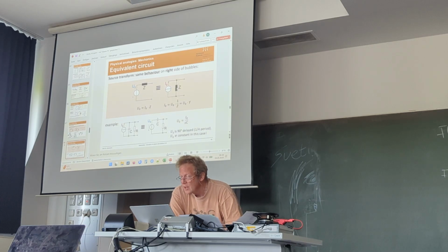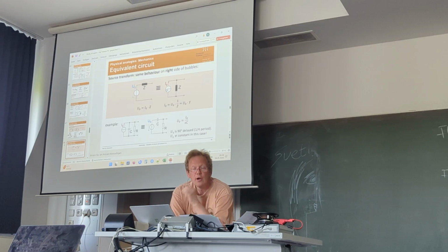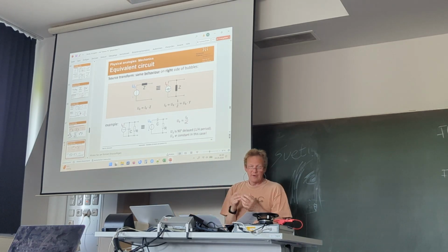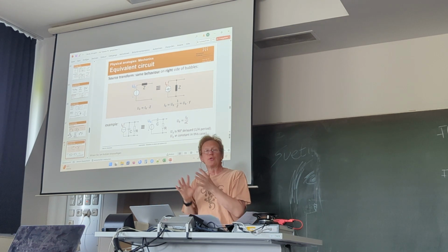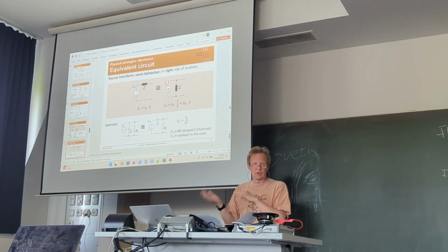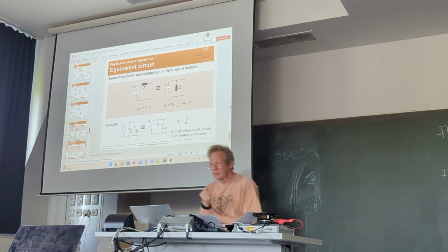There will be a voltage, and that means we have a continuous loss here. And if this is a battery, then it will be emptied after some time. So internally, for the source itself, it's not identical. But to everything attached to this source, it does not matter if it's a voltage or current source. That's the meaning of this transform.